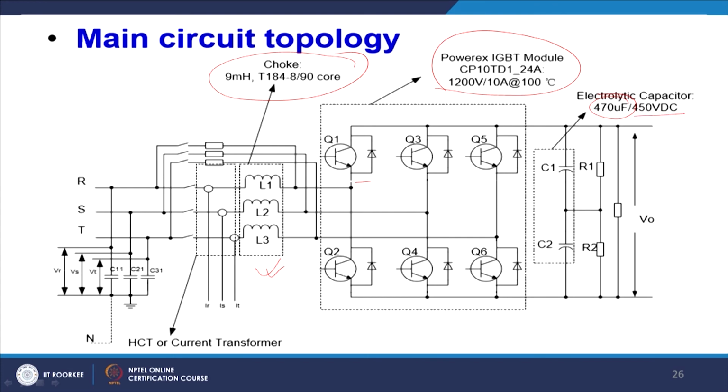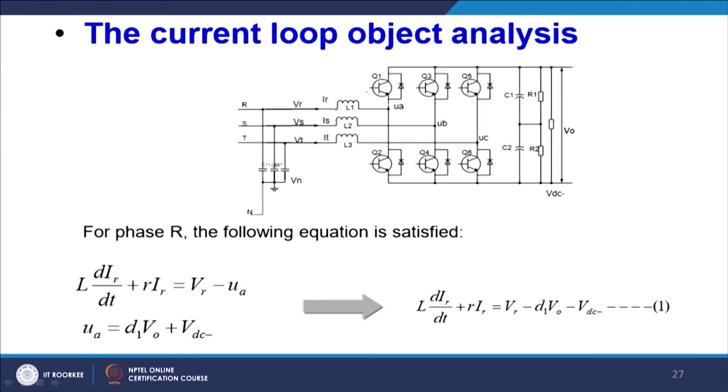You will find that this voltage will be around 700 volt, 750 volt, something like that. For this reason you will be using capacitors of the rating of 450 volt, so that 900 volt can be used. Now, these are the calculations, and control and all those aspects have to be there. So, this is the value of this.